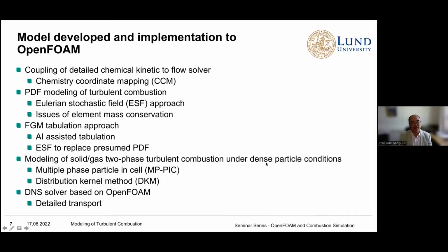Unlike a spray, which we assume, like a diesel spray, which we often treat as point particles where we don't consider volume, in a fluidized bed it's a dense particle situation, so particle collision has to be taken into account. So we got a code from NTNU, which is based on the multiphase particle-in-cell approach, and we further extended it, making it more robust and accurate by introducing a distribution kernel method, DKM.